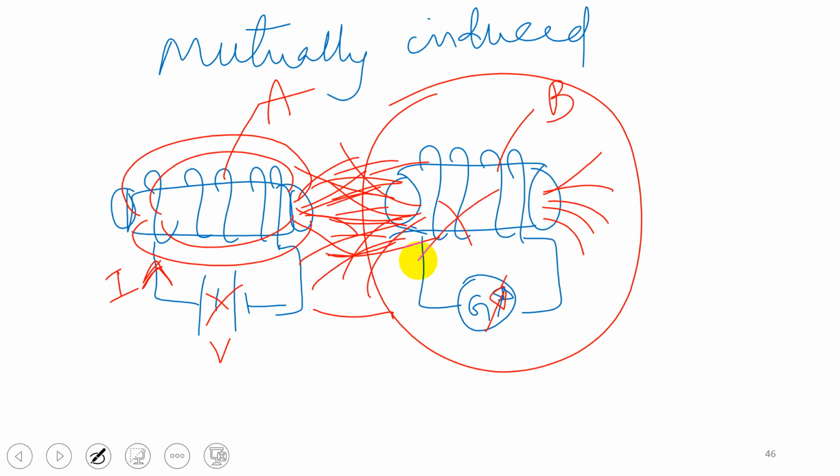As long as your voltage is constant, the current is constant, the flux is constant, and the flux linking coil B is also constant, correct? That is how it is possible. So if the current in coil A is constant, though the flux is linking the coils, there is no change in the flux linkage, then the EMF induced is zero.